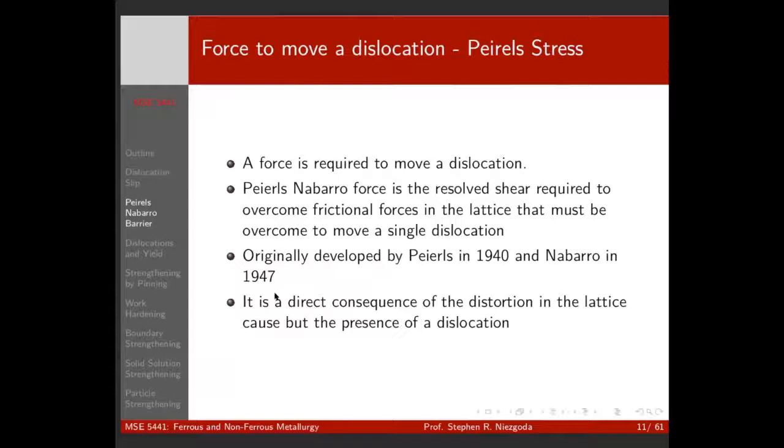In rock salt we have the complication that we have ionic bonds, but we also have the fact that dislocations have a charge associated with them because they're associated with point defects of the lattice, right? So in both of those systems, the dislocations are not mobile until you get to a high enough temperature. For diamond, that's after the temperature where it turns back to graphite, so you don't need to worry about that.